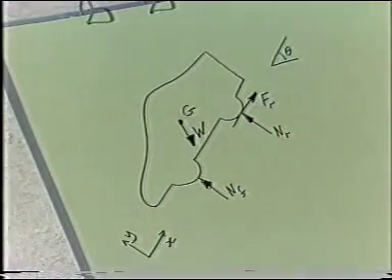That deals with the solid contact forces. What about fluid contact forces? The car is in contact with the air. There will be a small buoyancy force, actually about 50 newtons. And if it's windy, there'll be a fluid dynamic force too. But these should be relatively small, so I'll neglect them. So that completes the free body diagram. The car is stationary, so now we could do the equilibrium analysis to find FR. But I won't go through that detail now.